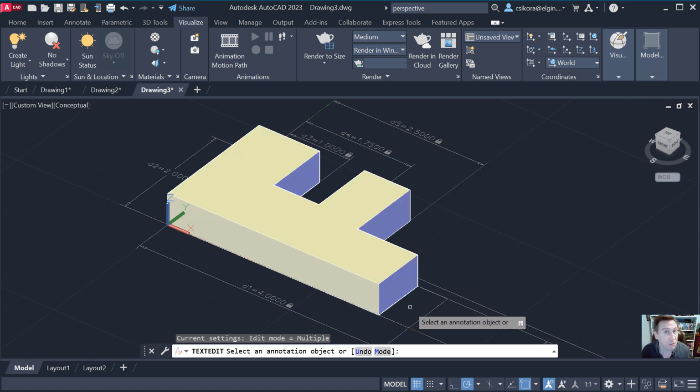Now, if you were to make this a surface, surfaces actually are parametric. They will update with it. If we extrude that instead of as a solid, there's an option as a surface. And we go into surfaces more in exercise 11. So we've got a ways to go before we start really looking at those.